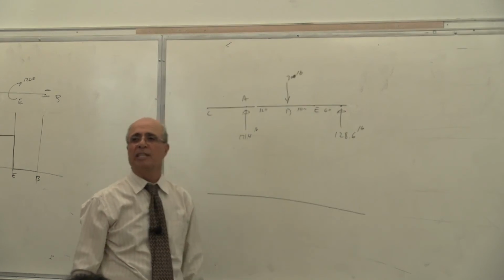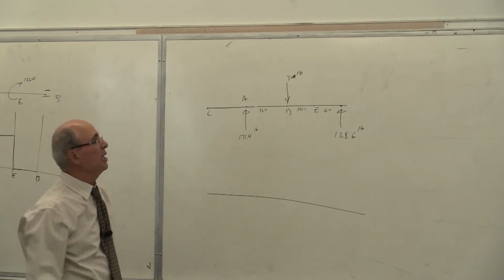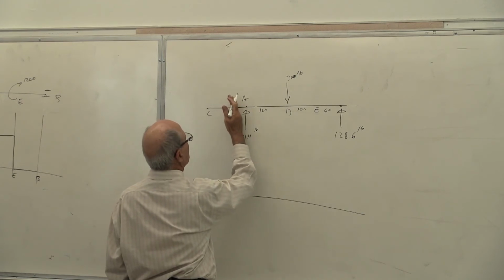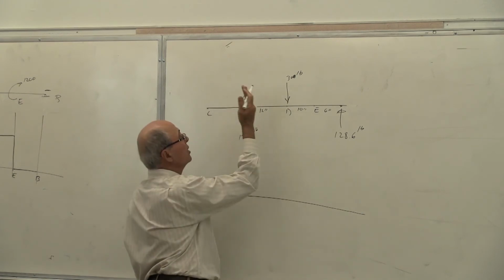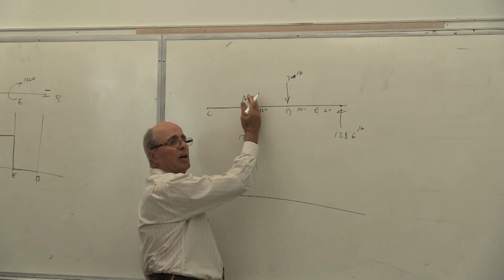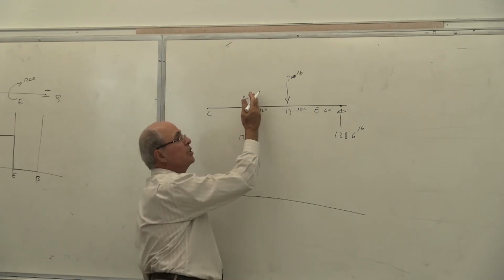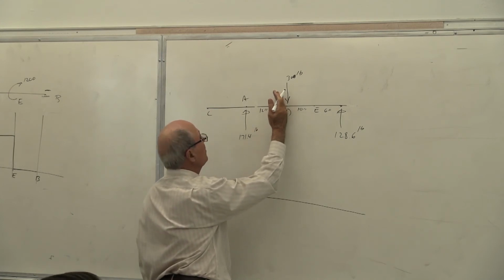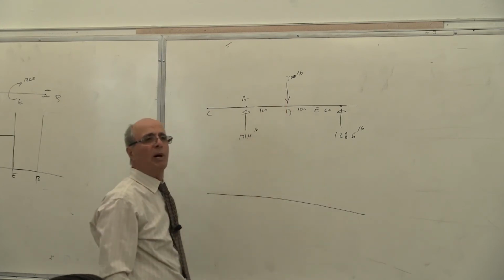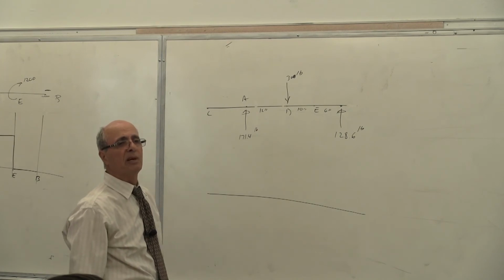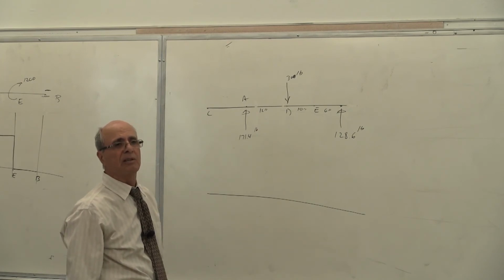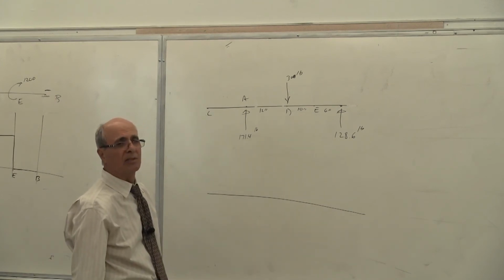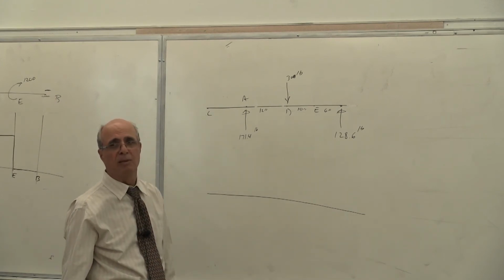M that we are using in ME218 is none of that. M is, you start from here, you go forward. M is 0, 0, 0, 0, 0. M is here, how much? At 1 inch, it's 171.4 times 1 inch. What's the moment here? Look at it. The moment here is 171.4 times 12 inches. That's the internal moment. This is the one that causes stress. Is that correct or not? So don't make that very bad mistake, I call it. Is that correct? But I have seen a lot of that, believe me.